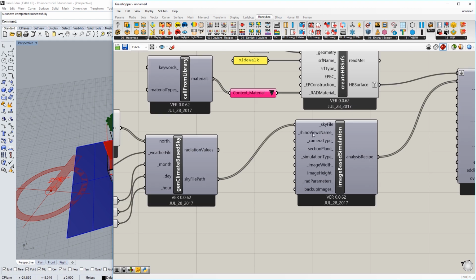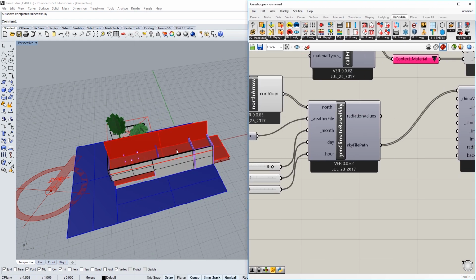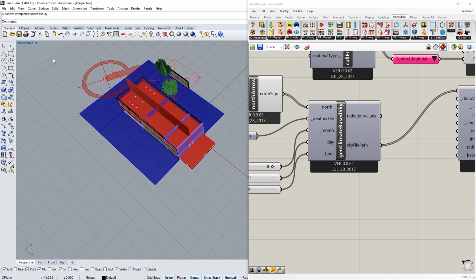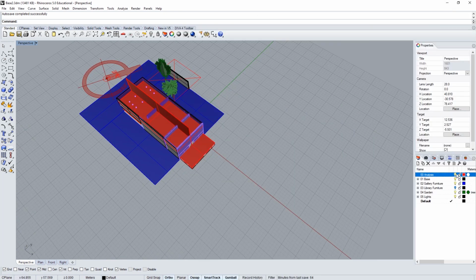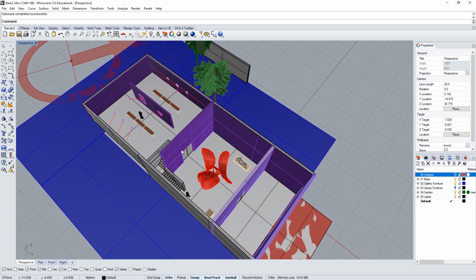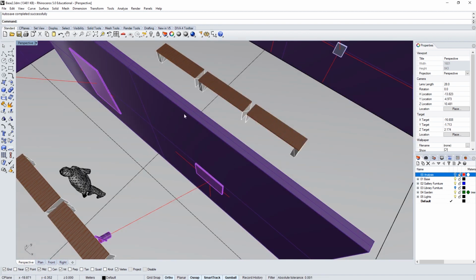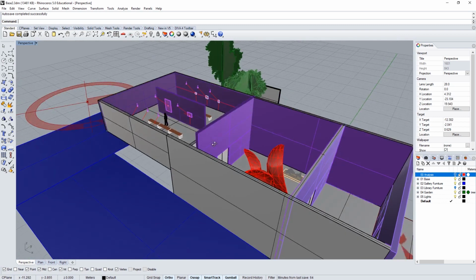So now we need the Rhino Views that we're going to use for the rendering, and right now we've got this on perspective view. Let's just keep this for now. The view is going to use whatever you've got in your viewport. So if you've got this zoomed in, then if it's like this, it will render this scene. If it's like this, it will render this scene.